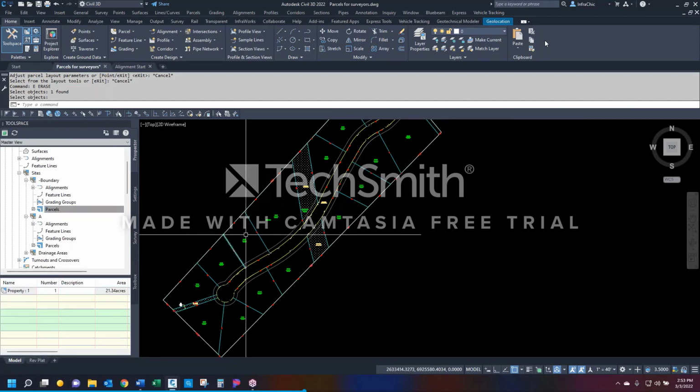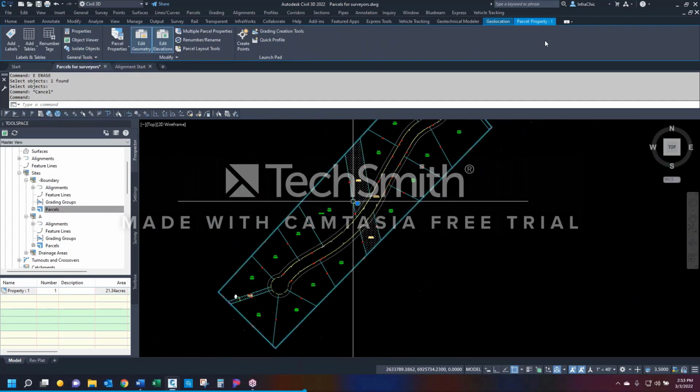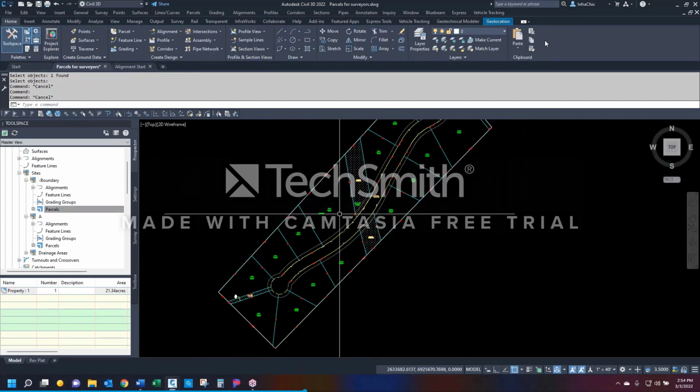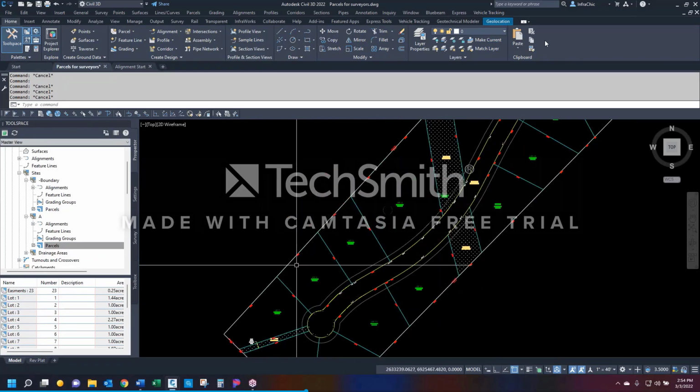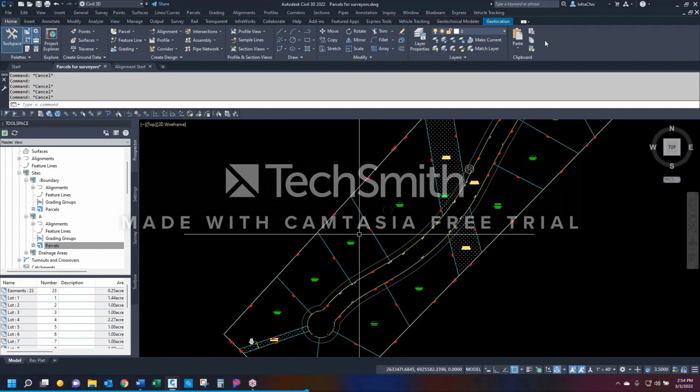Note that there's only one parcel here, and that parcel is still right here. That's its own boundary parcel. But this line work is different because there is no real boundary anymore. It's all open space, lots, all that, anything but a boundary. So there's really no property overall anymore. In order to change that back, you're going to have to go through and find that property style that was assigned the lot style to it and change it. Not easy to do, trust me. Kind of a pill. That's why I put them in two separate files, an XREF and the existing one, so that I can turn things on and off.